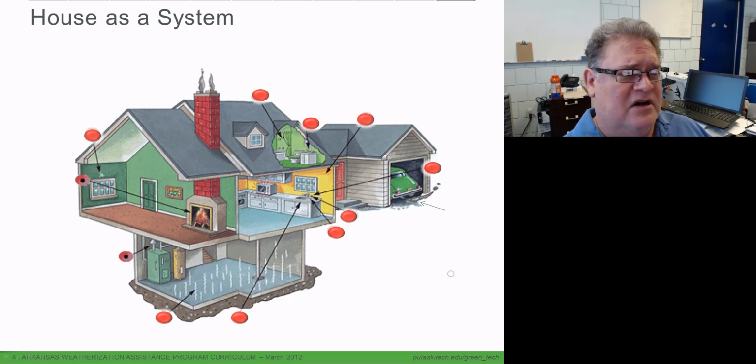Now, what kind of problems does this cause? Well, if we have missing insulation or cold spots like here in the kitchen around this window, or even better yet over here in the living room, you see this discoloration right here, that's representing condensation. So if we're heating the home in the winter, we may have cold air moving through this wall and maybe up the cathedral ceiling, or leaking from around this window, keeping this wall cooler than it should be, keeping it below the dew point of the air inside, so we're getting condensation there. Same thing may be happening over here in the kitchen.